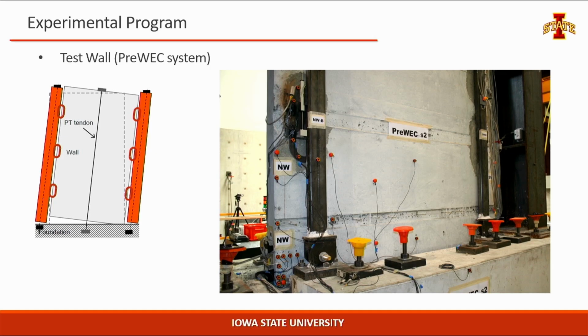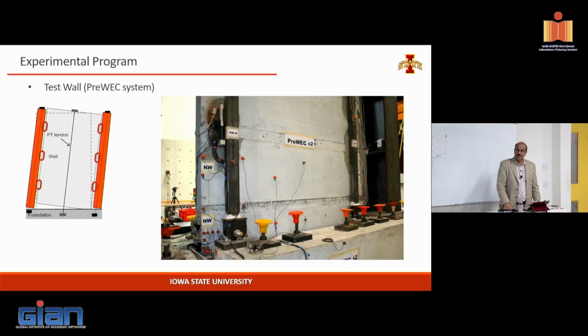All right. So we want to continue the discussion a little further. I just want you to see the different concepts that we are exercising, the flexibility that these systems can bring in. This is basically the detail we use to move the tube inside. Again, it's not possible in every structure, but this tube doesn't have to go all the way to the top. You can terminate it even within a floor and put larger connectors. There are a lot of ways you can play with these things.